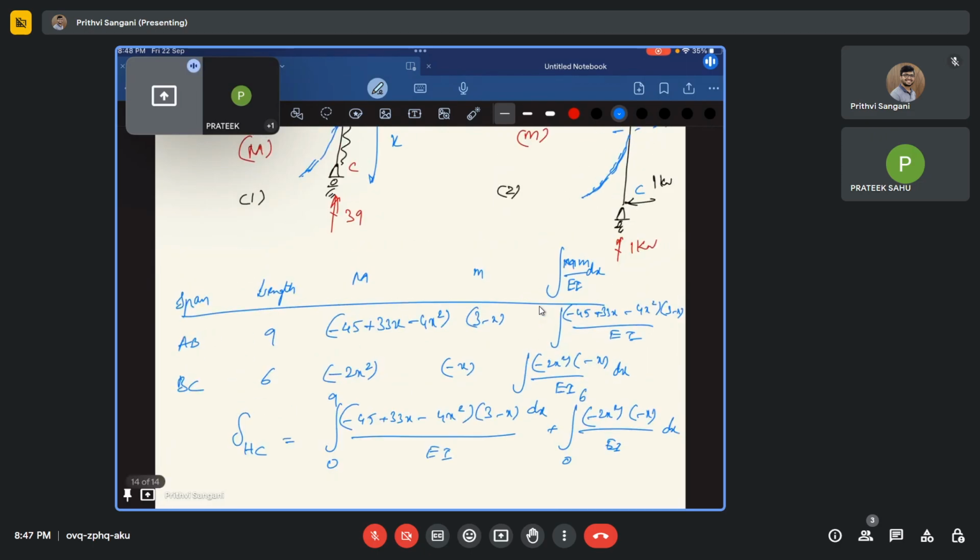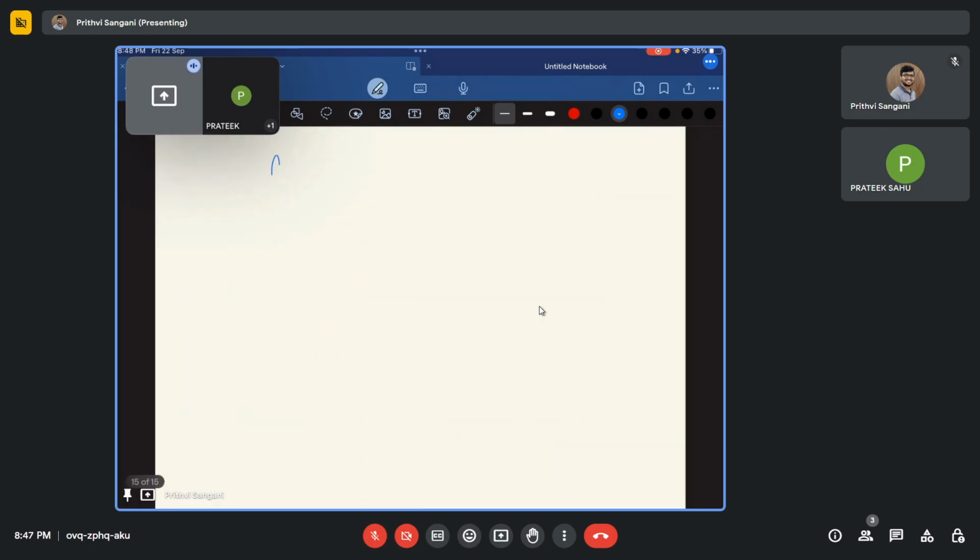So delta HC, if you solve that, you are going to get 243 by EI plus 648 by EI, 891 by EI, and this is going to be in this direction.